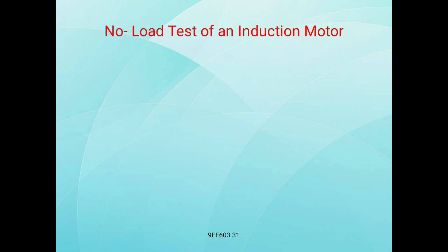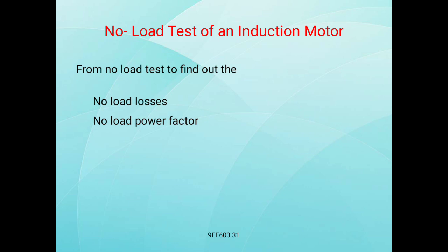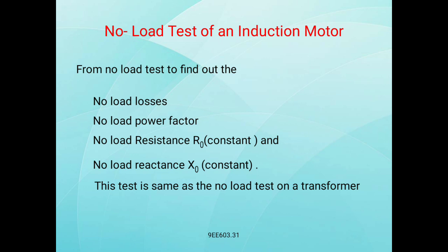In the no load test of an induction motor, we find out the no load losses, no load power factor, no load resistance R naught, and no load reactance X naught. This test is the same as the no load test on a transformer.